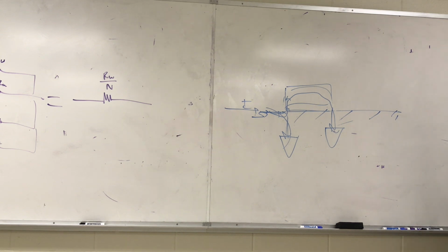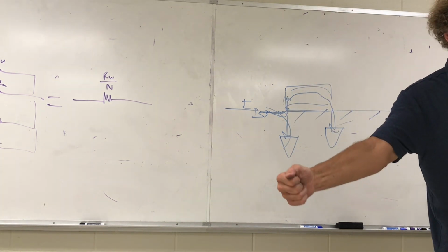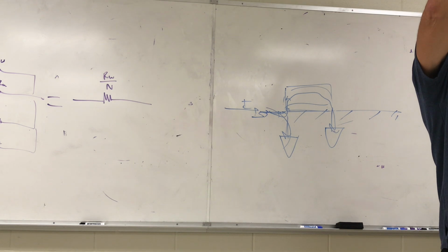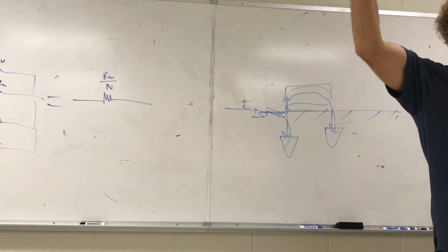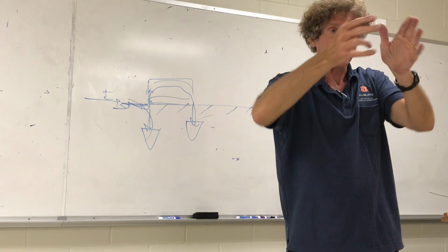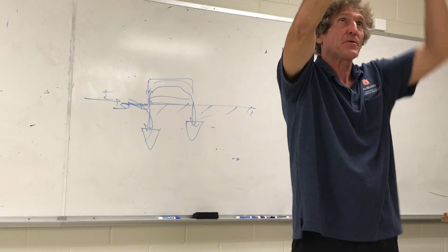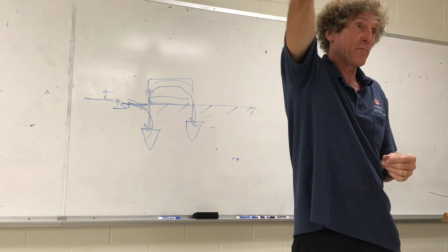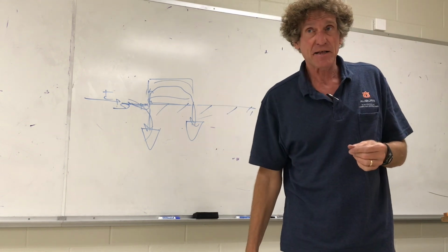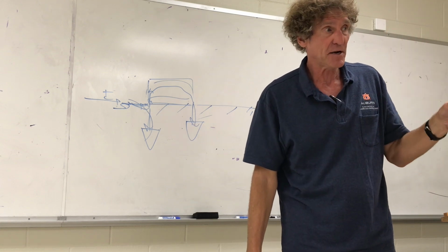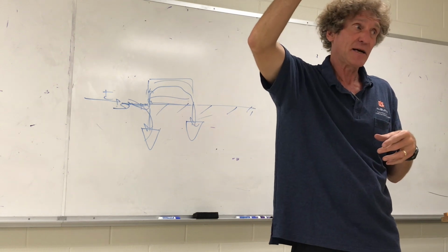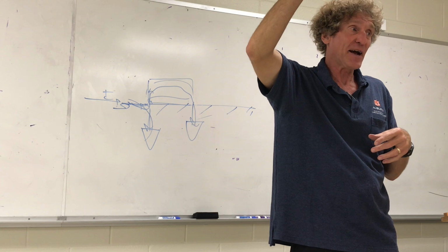Now that house had a unique problem. Usually it's easy to get a ground rod in one location. And then if you're in an area that gets hit by lightning a lot, you take a heavy gauge wire and hang it up, and it's called a cone of protection. You may have heard of this. If you want to protect the structure, you have to be up so that a 30-degree cone is formed by a guy wire that can take a lightning strike. And then you have ground rods on either side of that. It has to be electrically stout so it can take a huge amount of current. Then you won't have a problem. It'll be protected because the lightning won't hit your house. It'll hit that 99.99999% of the time. Guy had the equipment to do that, but he didn't put it up.